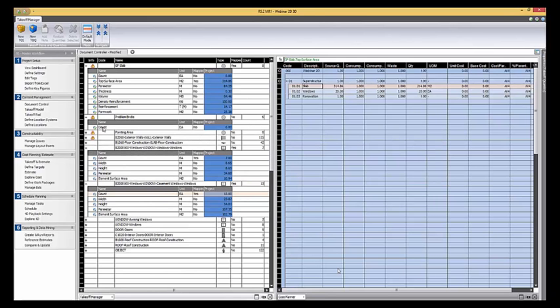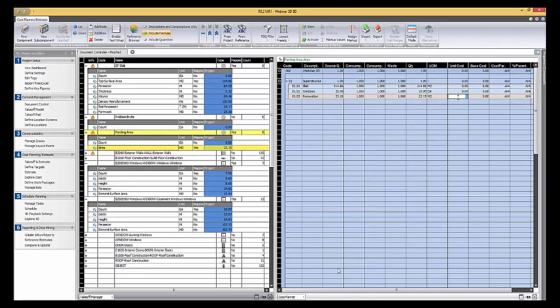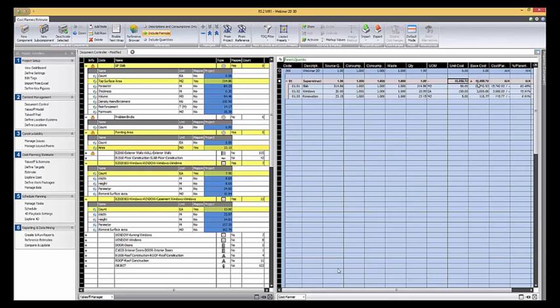Ooh, not the brick. So all that's left to do now is put a price against everything. So I'll just come in here. Everything in this cost plan can be played with. We've got 3-point estimating, we've got margins, markups, anything like that. But for now we're just going to put a base unit cost in and then activate the assembly to get us a total price of £18,858.